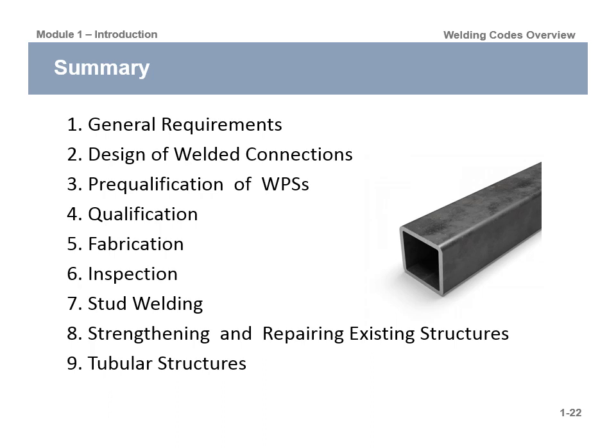Clause 3 is pre-qualification of welding procedure specifications. That's if we use a known material that's listed in clause 3, and we weld it with a filler material in clause 3 with a welding process that is pre-approved. We can't use gas tungsten arc welding, we can't use electrogas welding, we can't use gas metal arc welding short circuit and still be in the good graces of clause number 3.